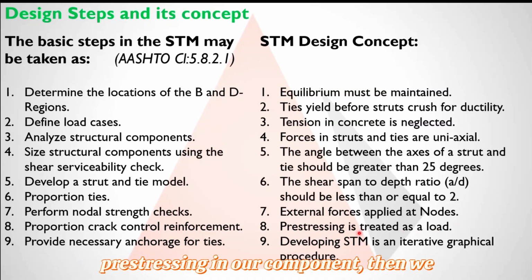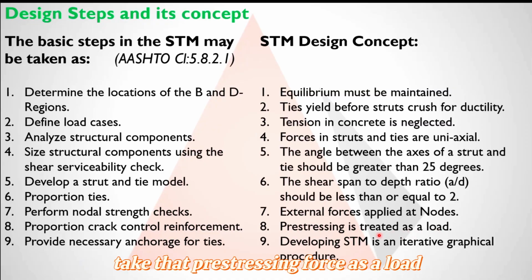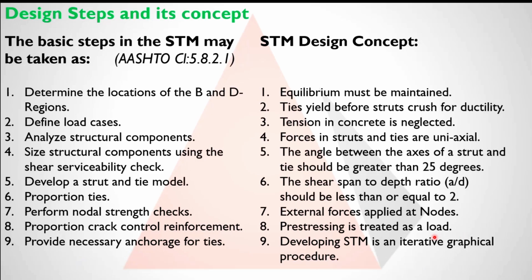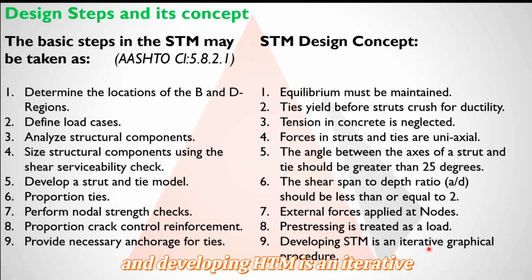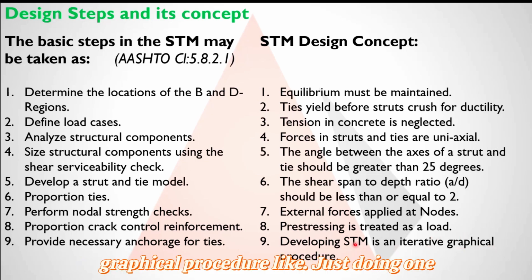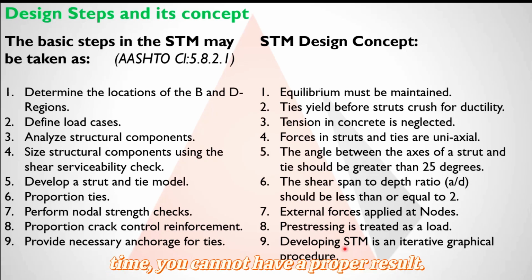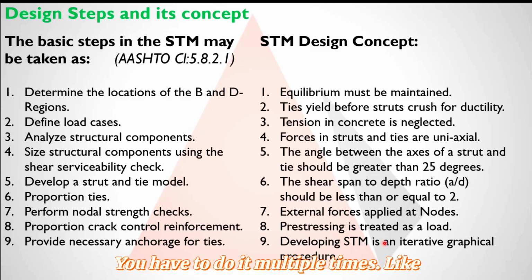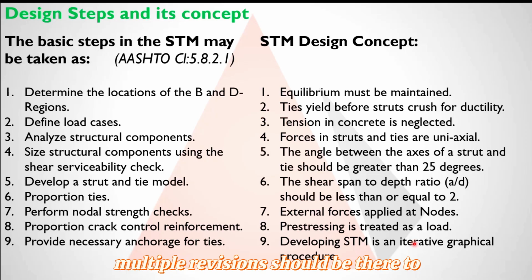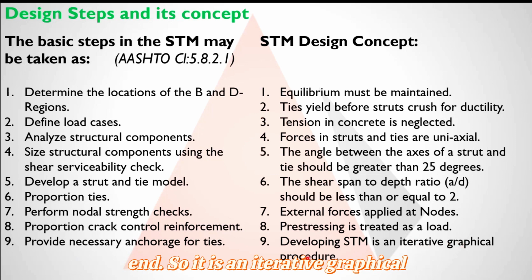If we have pre-stressing in our component, then we take that pre-stressing force as a load. And developing STM is an iterative graphical procedure. Just doing it one time, you cannot have a proper result. You have to do it multiple times, with multiple revisions, to have a proper optimized result at the end. So it is an iterative graphical procedure.